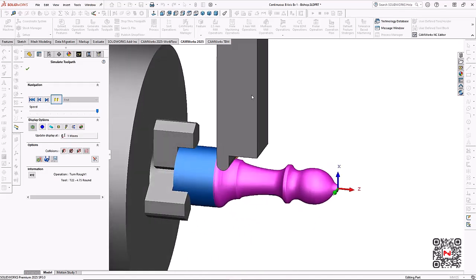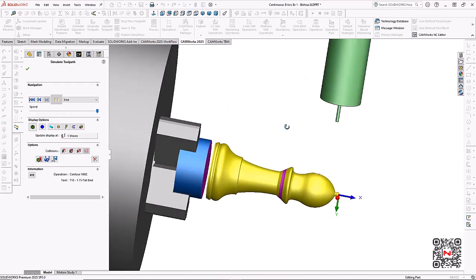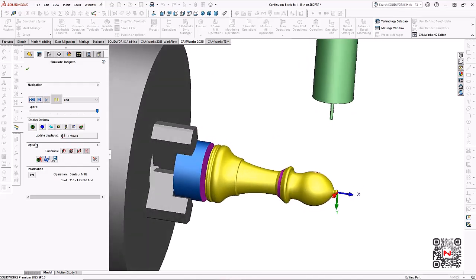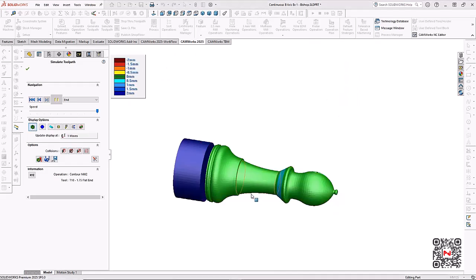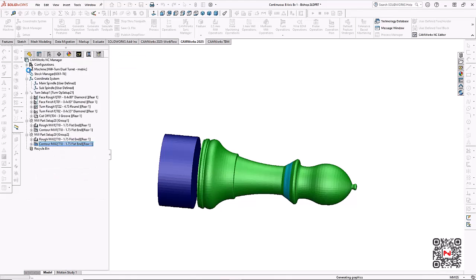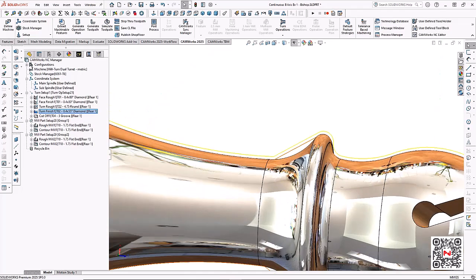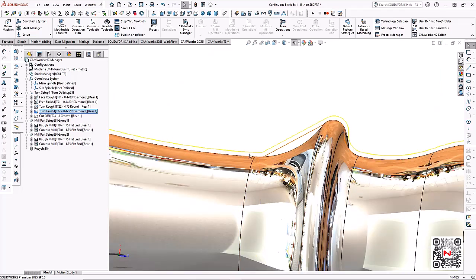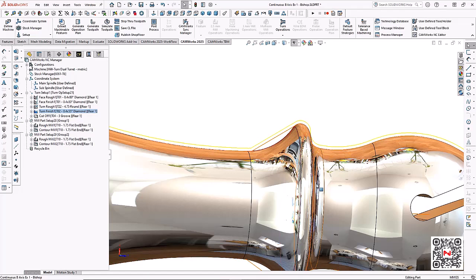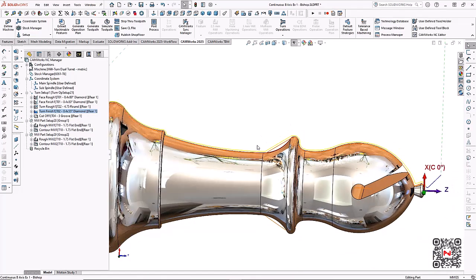And let me just rotate this view a little bit so we can see it a little better. And you can see that it has machined the part. If I compare the machined model to the design model, you can see here that everything in green is net to the design model, but you'll notice some blue here on the back of this flange. So if I go back to the turn finish, you'll see here where there's some material left on the back of this flange. That's because of the 55-degree diamond and holder that I'm using to do the machining.